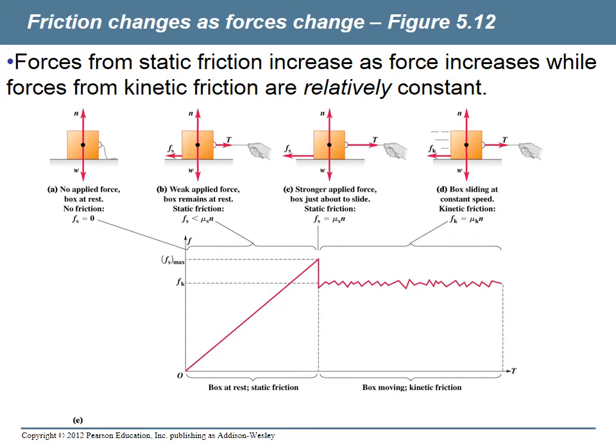And you would figure out the normal force, which would happen to be 500 Newtons, and I would give you a coefficient of static friction. You would figure out what that is and say, all right, that's the point it would start moving. Now, if that's less than my 10 Newtons I'm pushing on it with, then by all means it'll move. If this maximum frictional force is more, then it won't move.